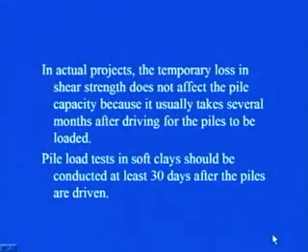Pile load tests in soft clays should be conducted at least 30 days after the piles are driven, such that the piles can fully mobilize the resistance which they are supposed to offer while working under the load which is coming from the superstructure.